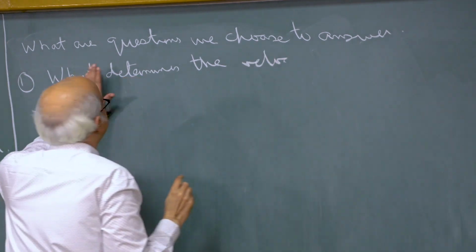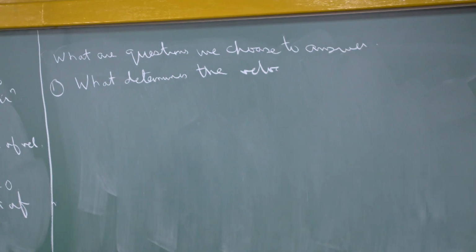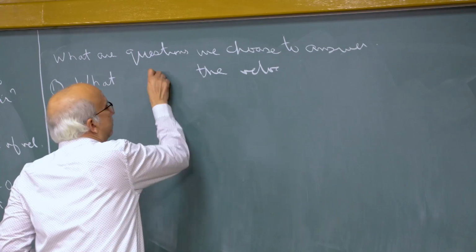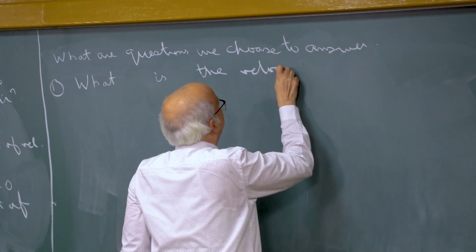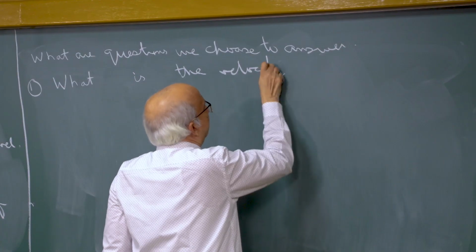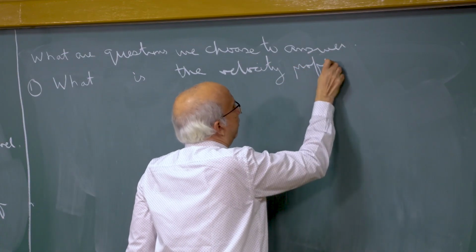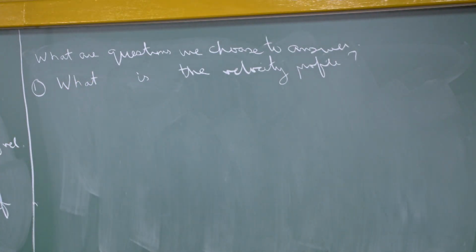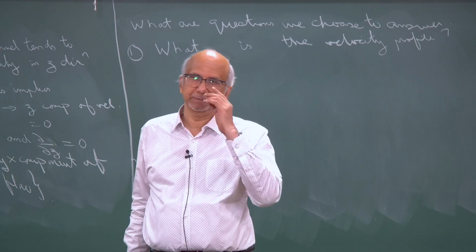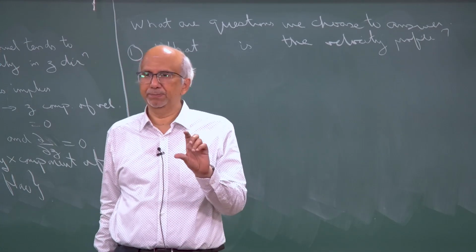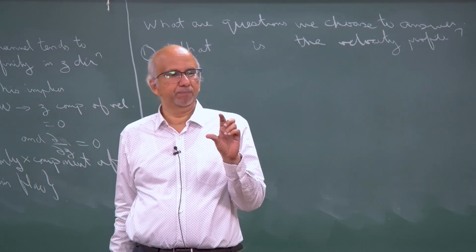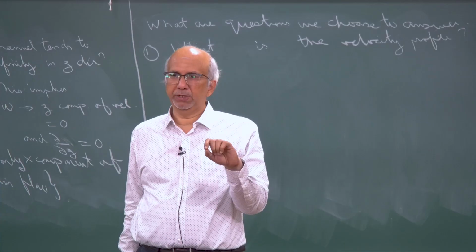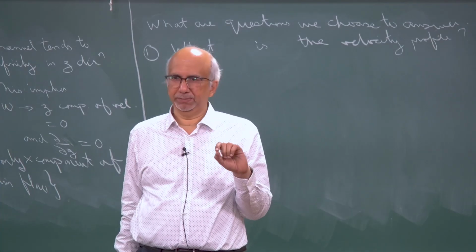Yeah. So, the first thing is velocity profile. What is the velocity profile, right. Velocity profile. Okay. The other question which you may be interested in is trying to relate the volume fraction occupied by each phase to the flow rate fraction that you are pumping in.